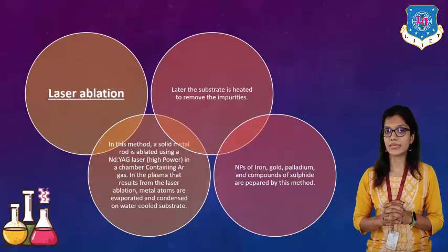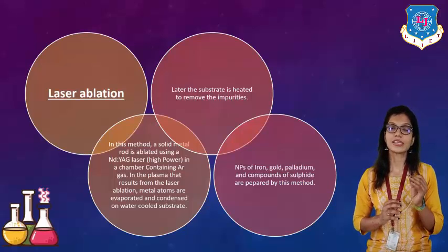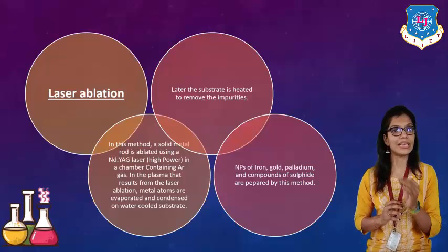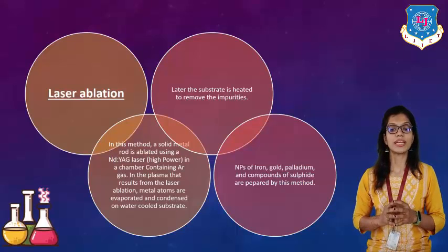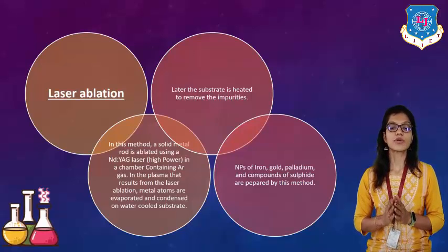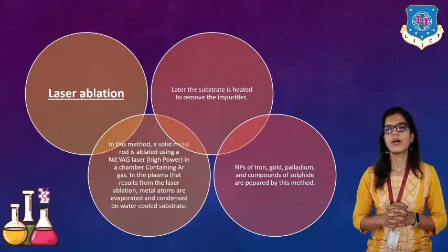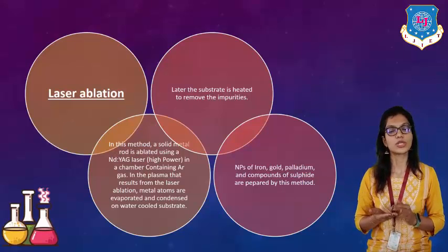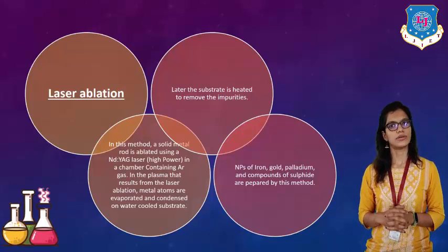The NdYAG laser, at very high power, is used in a chamber containing argon gas. Now, in the plasma that results from the laser ablation, metal atoms are evaporated and condensed on a water-cooled substrate. We should have a water-cooled substrate so that they can get condensed and placed on it. Understand it properly.